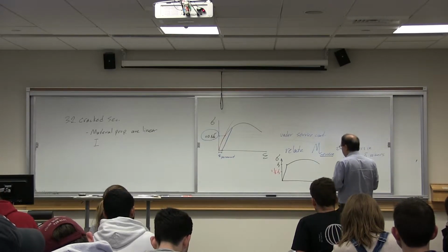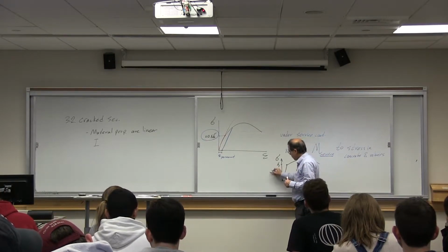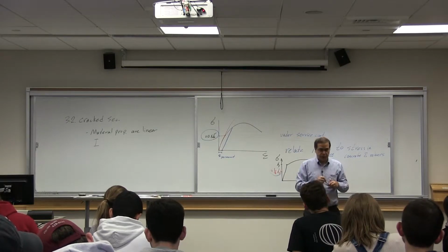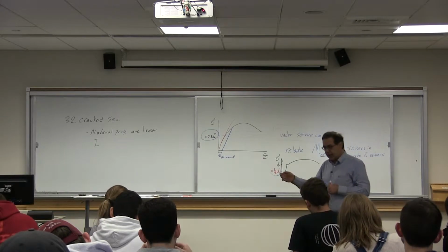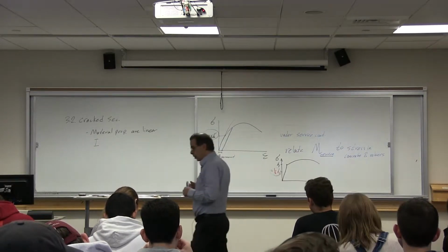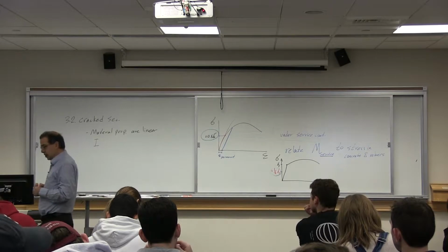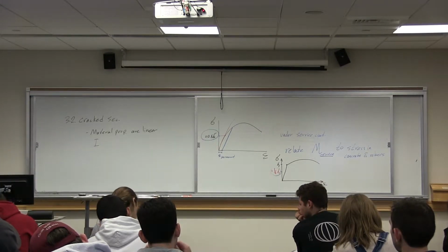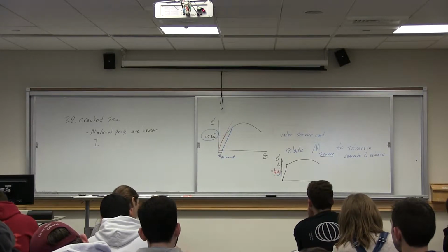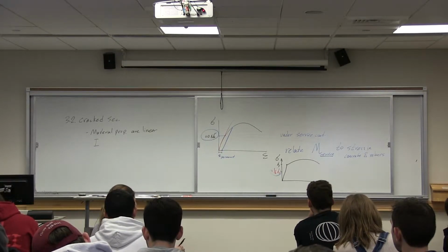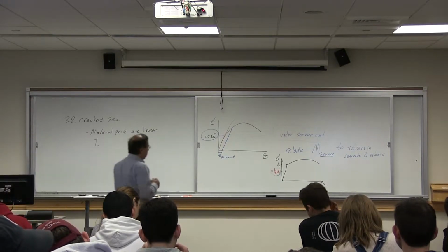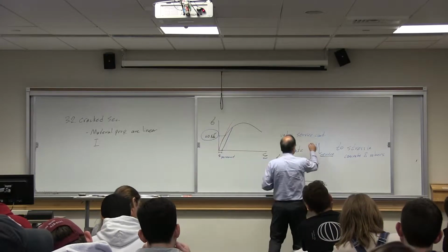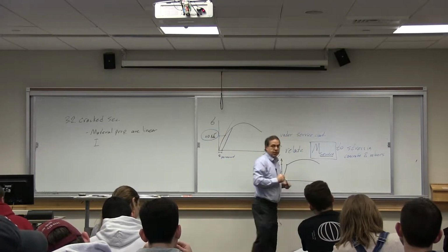And if we limit the stress in rebars to approximately 1/2 of Fy, not only do we have rebar that is linear and as a result of unloading would not have any damages, but also we control the crack size to a reasonable opening. Two constraints. What are those two constraints? The constraints are when you are looking at service condition.